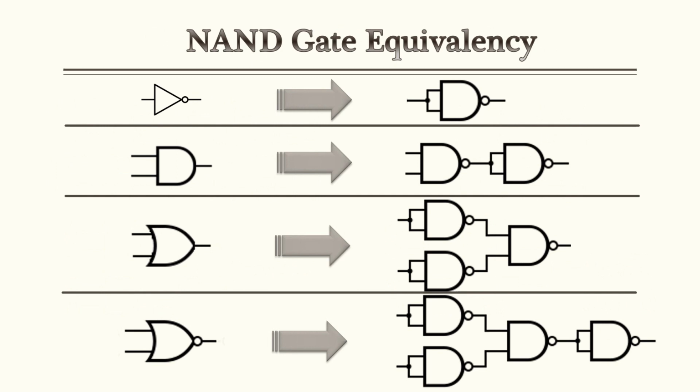Here's a representation of how the NAND gate is known as the universal gate. By utilizing different combinations of NAND gates, we're able to create the other gates as you see on the left. The one you really want to put a pin in and make part of your muscle memory is the inverter, or NOT. If you're able to understand and remember that one, doing the method later on to convert any circuit to NAND gates will be easier. Try not to memorize or get stuck on how to create the other gates, because you will not be utilizing those in that method. So we'll go on and practice later on how we create a NAND gate circuit.